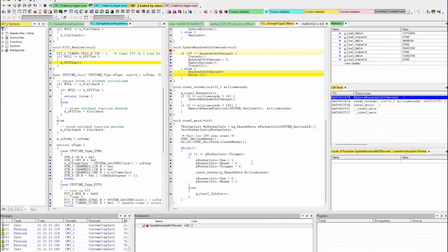Okay, this debug synchronization is enabled by default, but you can of course change it if, for example, you want to debug some independent applications that are running on the several cores here, and you do not want to influence a specific core and want to focus only on core 0 or something like that.